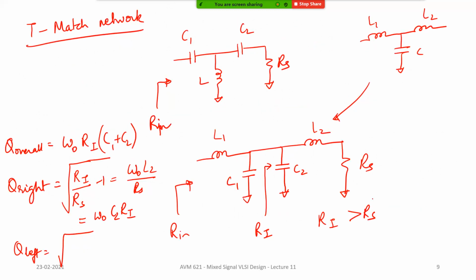Where you take the impedance higher, so you will probably take 50 ohm to something like 70-75 ohms, and then you bring it down all the way to 12.5 or whatever you need. Okay, so this divided by Rin minus 1. Again, you can write the equation very similarly. The approach is very similar, same type of equations you write, and same design procedure is followed.